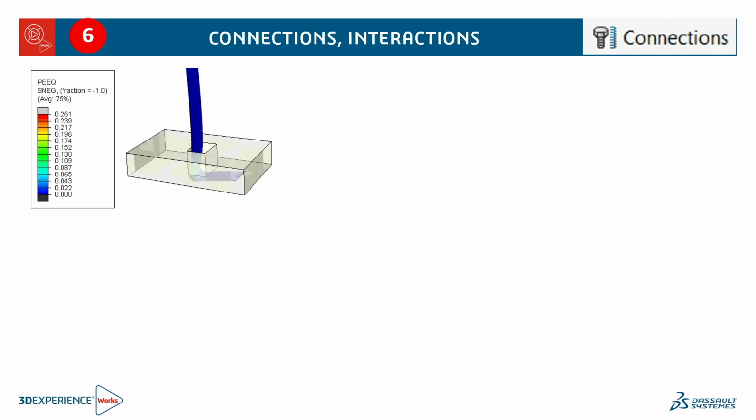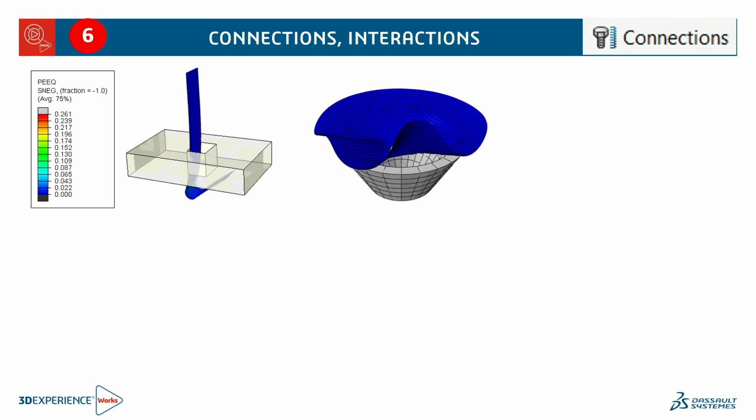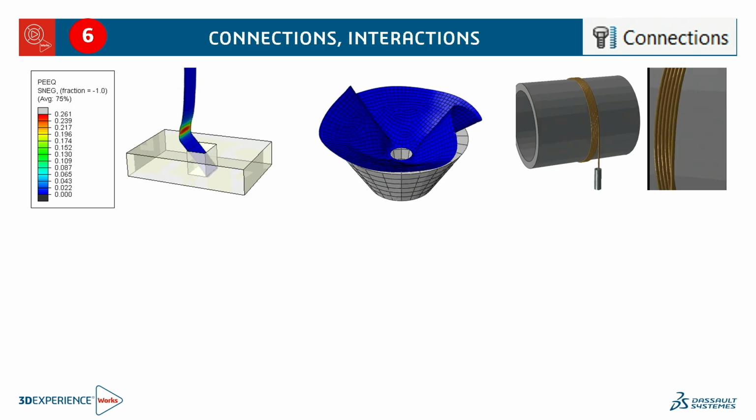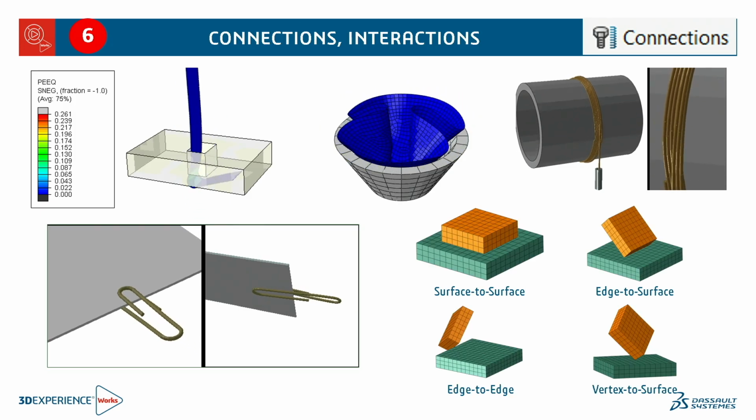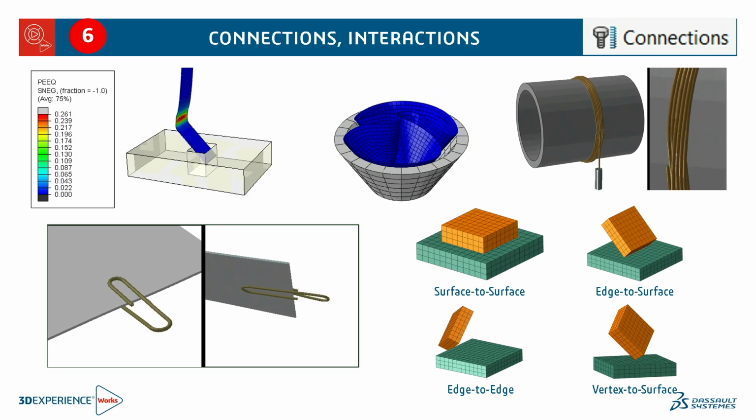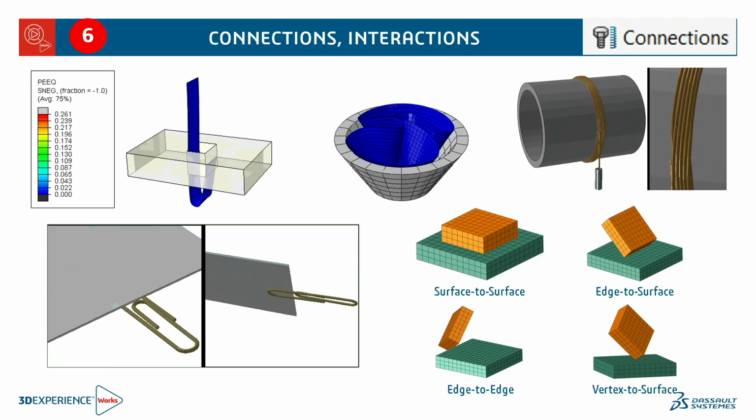So that was kind of the main thing. And I think for contacts, this is where I would recommend you start thinking about 3D experience. If you're ending up with large numbers of parts with large relative motions and it's just getting complicated to define the contact pairs, we can use general contact and run through all types of different analysis situations. This clip going into the slot is showing edge-to-face contact developing through the analysis.